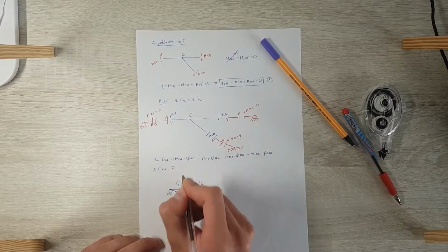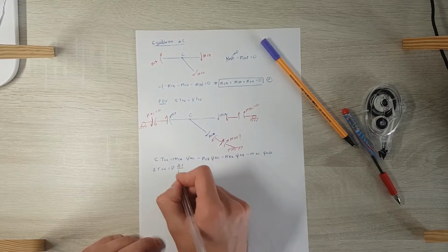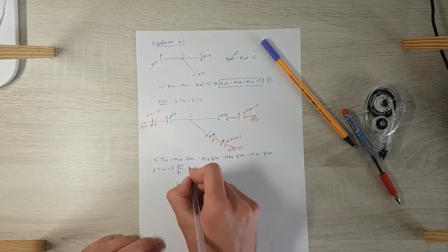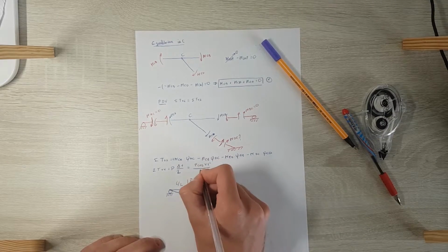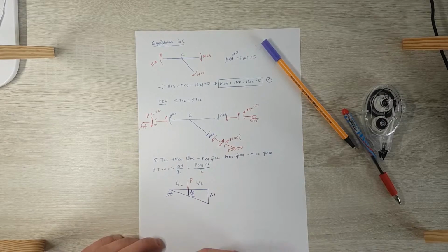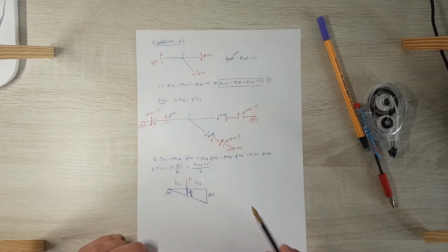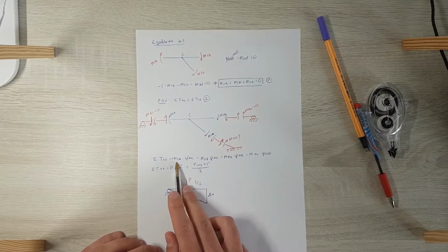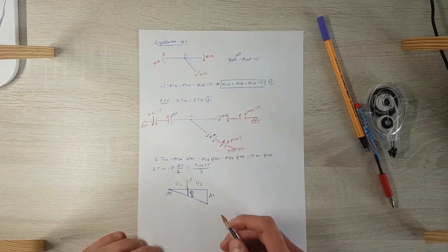So the load times the virtual displacement, and by the relations between delta and delta 1 we can finally deduce that this is P cosine of 45 divided by 2. And finally, by taking the external work and internal work equal, and substituting the values calculated before of all these moments, we have the second equation to solve the system.